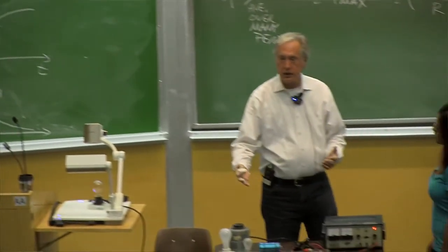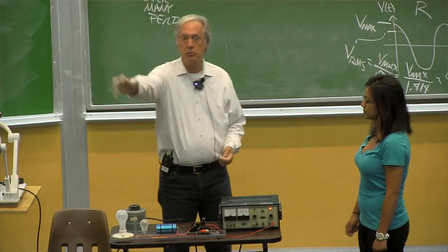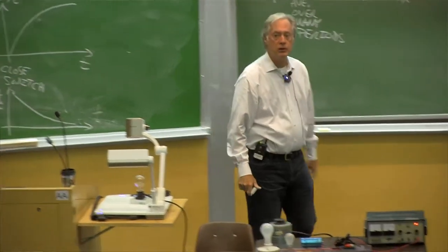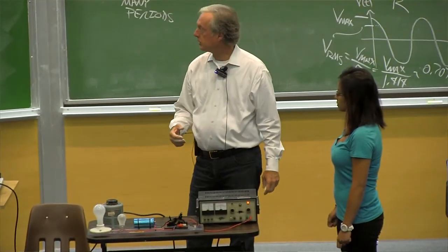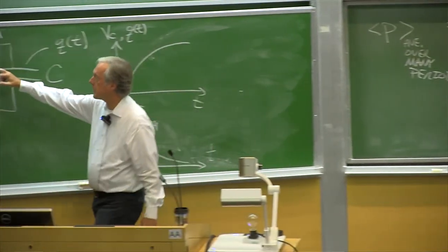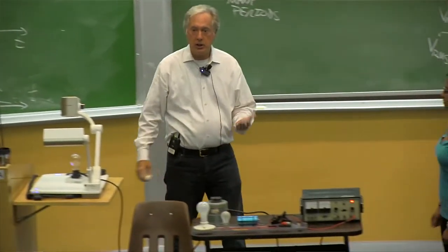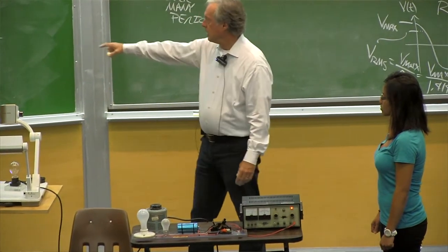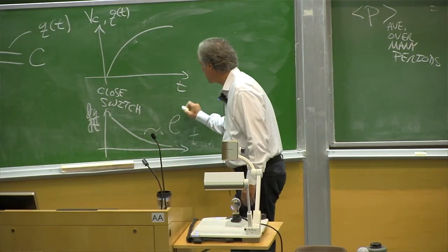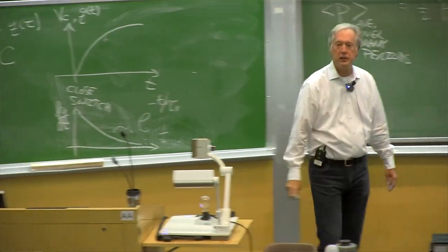As we get more charge on the capacitor, now that charge is there, the next little bit of dq to bring in on the current is not going to have the full voltage across to push it in. So as we get more and more charge there, there's going to be less and less push to get more charge onto the capacitor. So the charging slows down. What kind of curve does that look like? Doesn't that look like e to the minus t over some kind of time, an exponential decay?